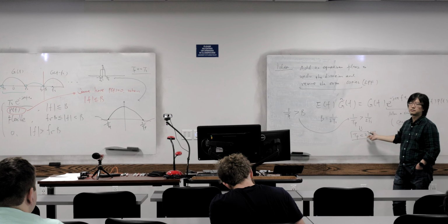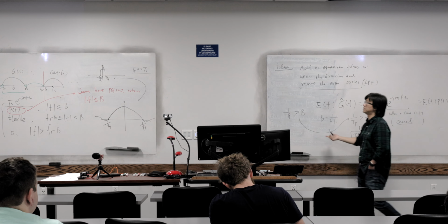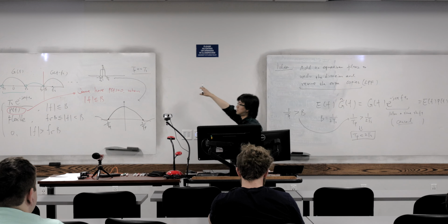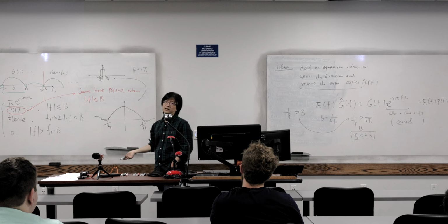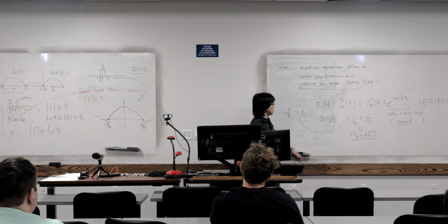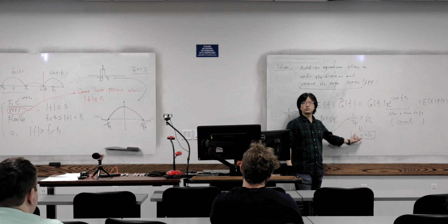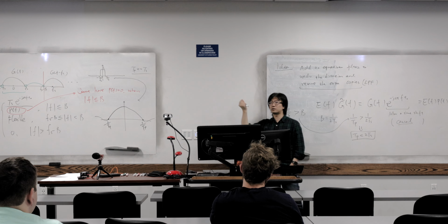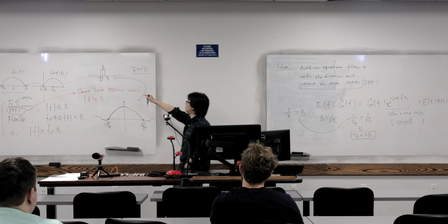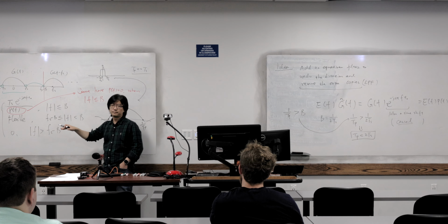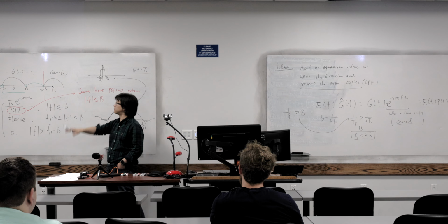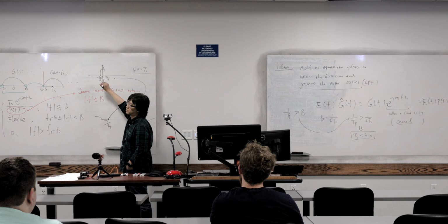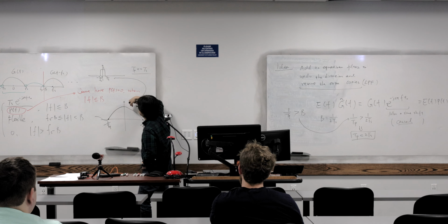Is that true? Of course. We assume TP is much less than TS. Of course, TP is less than 2 TS. In other words, if we use TS here, not TP, so make the width as wide as the sampling period, it still works. Basically, the narrow pulse or a bigger pulse, both of them will work, okay? But the advantage of using that is that this will be very flat.